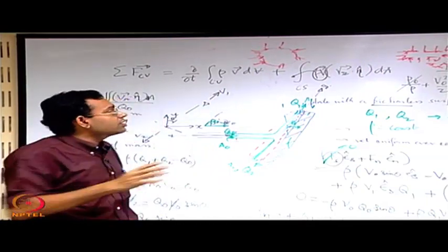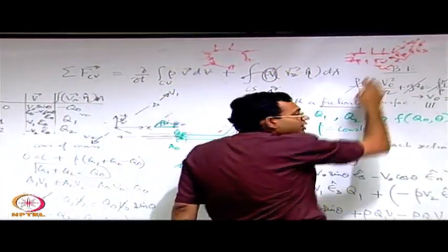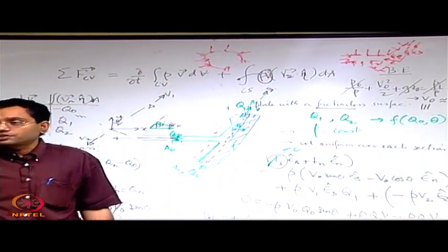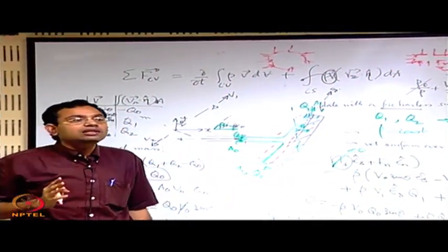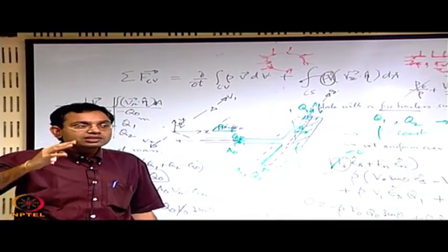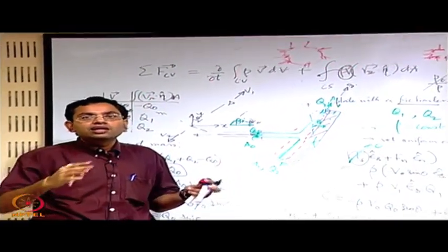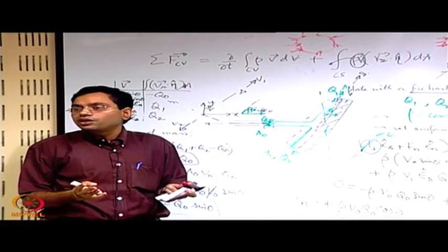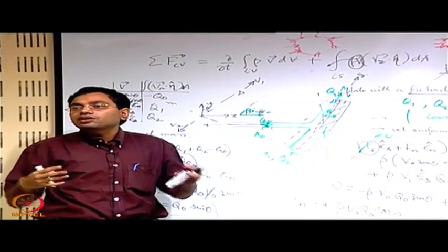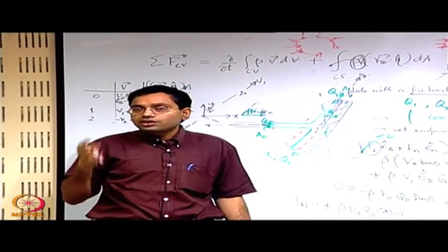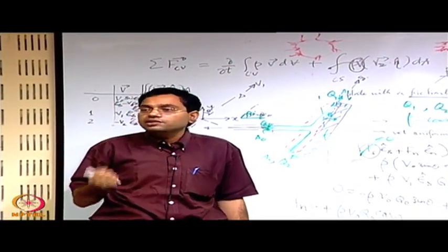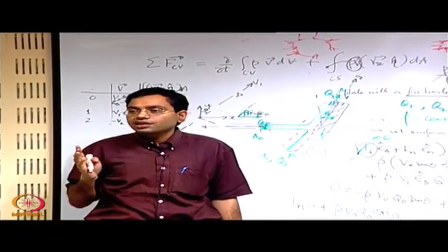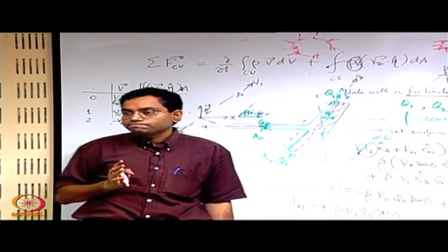So always when we consider forces here due to pressure, we consider the gauge pressures at different sections, because the deviation from atmospheric pressure is what is interesting for us. Atmospheric pressure, if it was the sole feature, it would have existed throughout equally and it would have given rise to a 0 net force. So in terms of giving rise to a net force, any deviation from atmospheric pressure is important. So the gauge pressure is the important quantity.